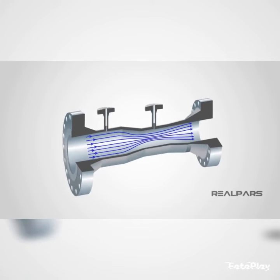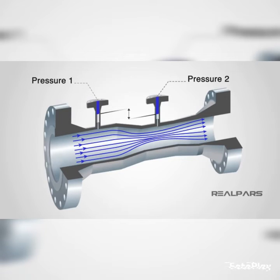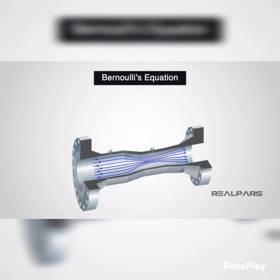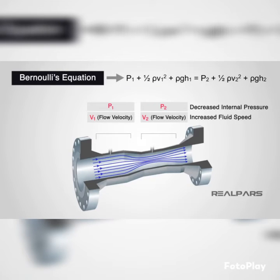One very common way of measuring flow using a DP transmitter is for the primary element to introduce a constriction in the pipe. Using a restrictive element on the primary side will create a high and low pressure. When the flow increases, more pressure drop is created. As we remember, the secondary element will measure the difference in pressure created by the primary element.